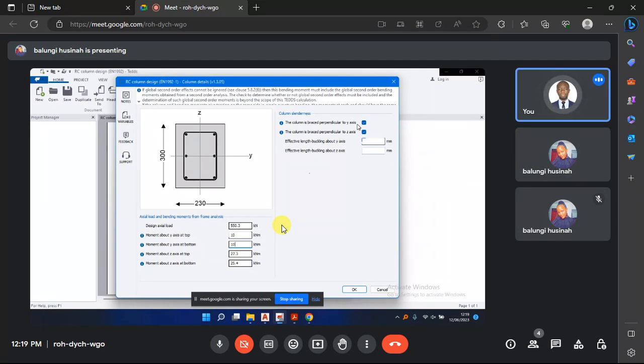If you have seen some steel columns, we sometimes brace them, those X forms of reinforcement, like angle sections. But I don't think there's any bracing here. The only thing I know is here, the column is fixed at the top and also fixed at the bottom because it does not move. That's how it is analyzed. But I don't think there's any other bracing.